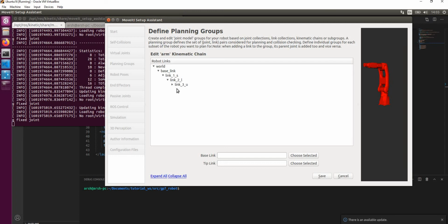Because you cannot have cyclic chains in any URDF. Even if you try to write it, it will give you an error. By cyclic, I mean that for example, link 6 cannot be the parent for link world 1 or any of the above links, because it will make a cycle in the parent-child relationship. And a URDF can only be a robot.